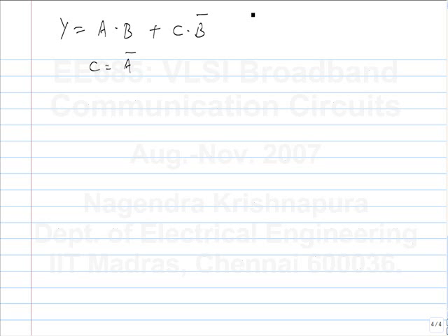What else did we need for our serializer and deserializer? In fact, our discussion on these logic gates will be limited to what we want to do there, right? That's why we went to this discussion. We want to make serializers and deserializers at high speeds, and we found that CMOS logic is not the suitable family for high speeds. So we came to this. So we needed a multiplexer there, and we needed some logic elements like inversion and so on. All those things we know how to make. What else do we need?